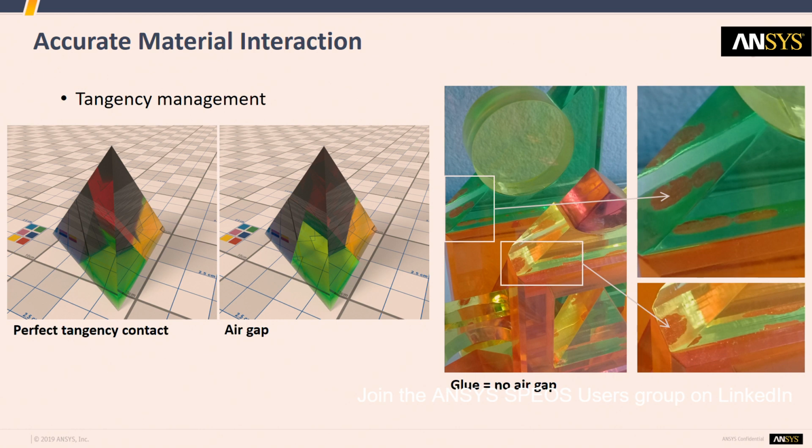That's something you can see on this photo, where in between those plastic parts you can see the dots of glue, and when there is glue, the light can go through, while where glue is not there, there is air, and so the light is reflected back.